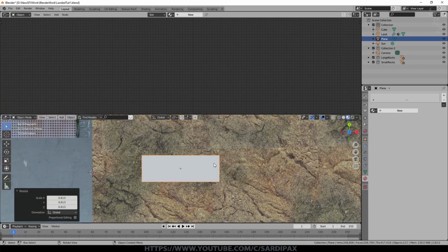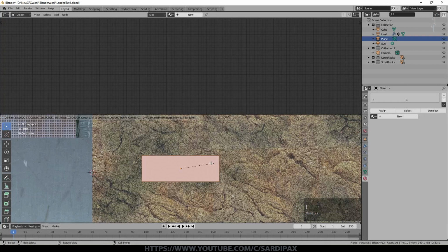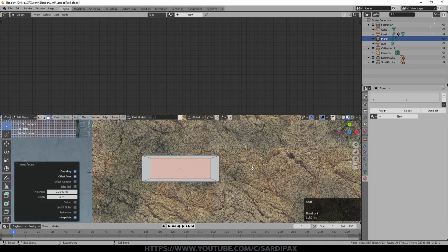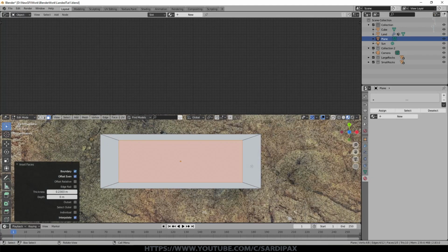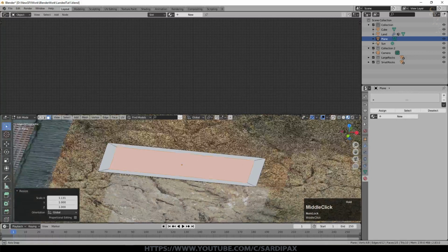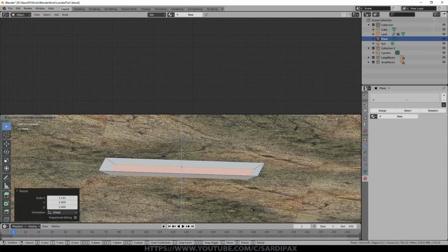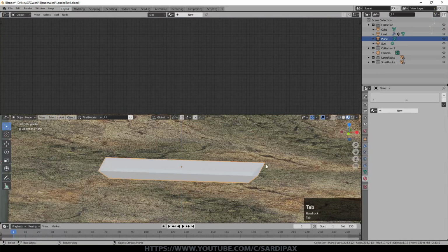And then I'm just going to go into edit mode, press I, which inserts. And because of the aspect of the shape, I've got bigger gaps here. So I'm going to now scale on X just to even that up. Now coming round, G Z, just to give me a sort of shape to the light, because we're using Cycles for this, so we can use meshes as lights.